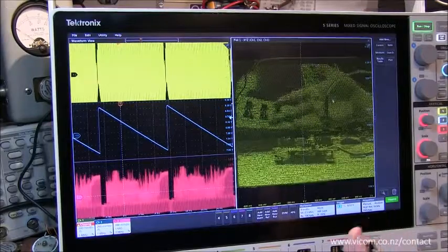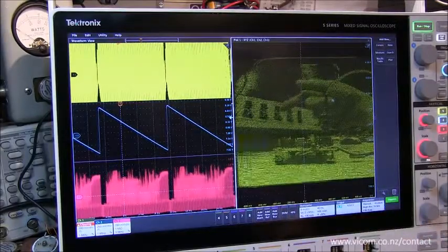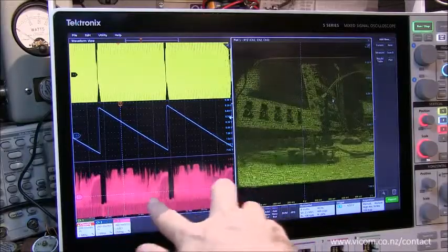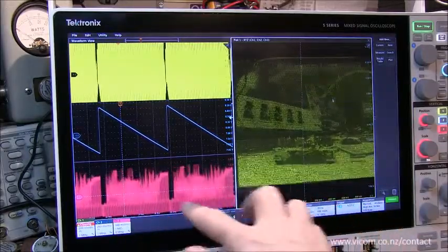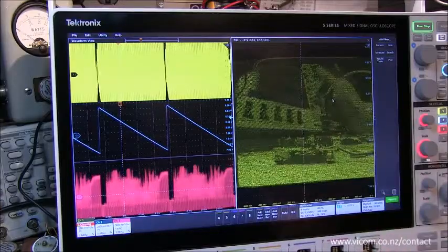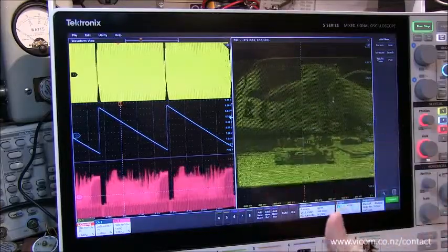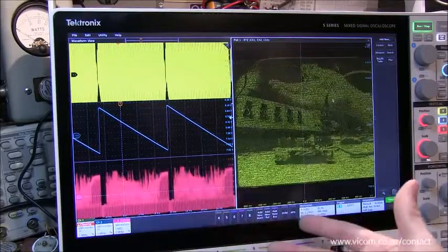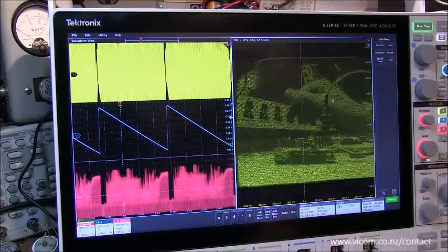Now, of course, the composite video that we're getting here is a little grainy, and that's because I've really only got 2 video frames, or 2 full frames being shown, and so we're not getting enough to really fill in the display. But it gives me a nice lively update because we're only grabbing about 40 milliseconds worth of data, so I'm getting a new update about every 40 milliseconds here.